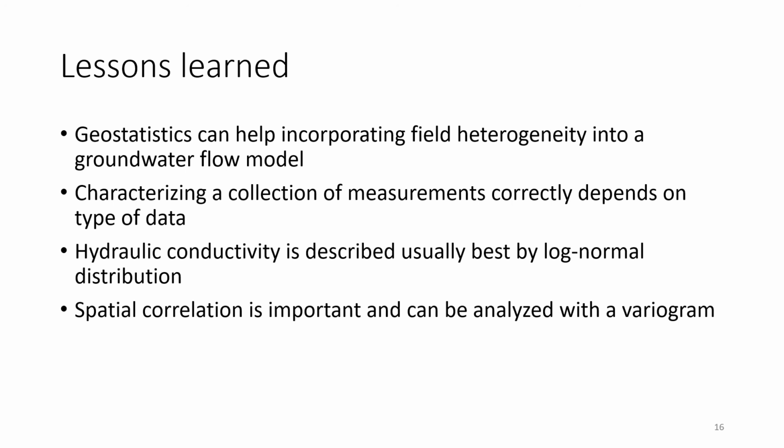So there are, as I said, different methods. We really just scratched the surface with the different kinds of means in the lognormal distribution for the hydraulic conductivity. But those are already crucial methods, two examples of how you can handle it. Keeping in mind that porosity is a bit easier because it's usually within one range, but hydraulic conductivity, because it can spread across so many decades, requires a bit more attention. And then finally having this important idea about the spatial correlations, right?